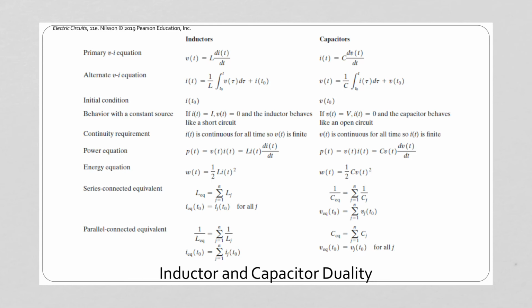If we are in equilibrium, where we are connected to a constant source, an inductor is just a coil of wire, and so at equilibrium, the inductor acts as just a wire. The current is some constant amount, the voltage is zero. A capacitor is opposite. A capacitor acts like an open circuit, so at equilibrium, the current through the capacitor is zero, and the voltage should be some constant value.